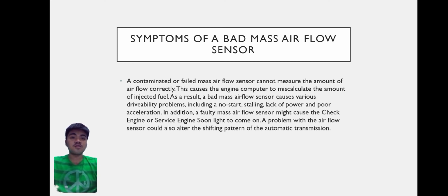In addition, a faulty mass airflow sensor might cause the check engine or service engine soon light to come on. A problem with the airflow sensor could also alter the shifting pattern of the automatic transmission.